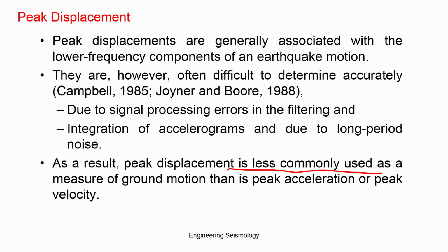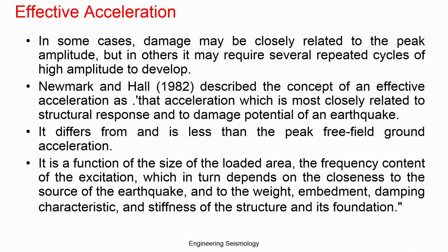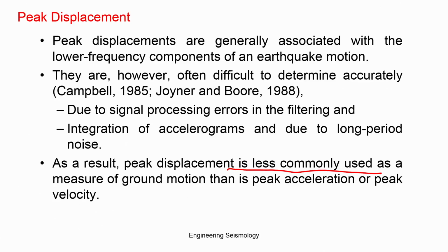So, this is used very little in engineering, but nowadays there is a displacement based approach, where they consider the displacement parameters for the design of those kinds of structures, particularly the low frequency structures, where the peak displacement is used as a parameter to design.